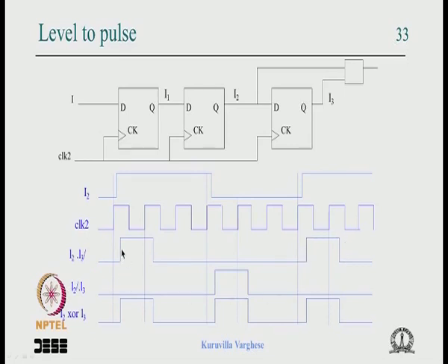And very important, the timing is correct because we are deriving it with a delay with respect to this clock edge. That pulse will come with a delay, and when this pulse ultimately goes to the state machine, it will correctly sample it as high.